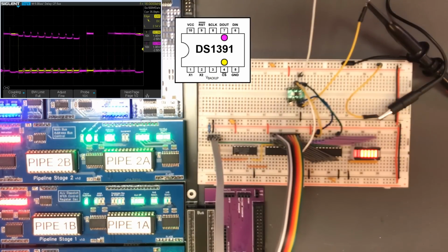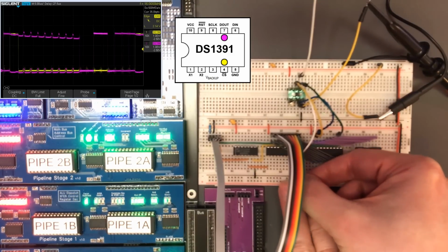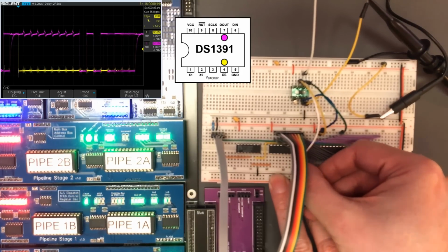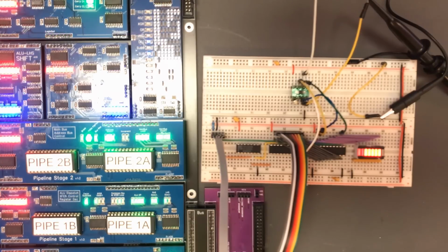Excellent. So that feels like we're seeing some rapid binary counting. It's a little bit odd at the start, but the data out is a tri-state. So only when it's outputting data will it drive the line. So I'm going to try putting a pull-up resistor in. That feels a bit more sensible. So what we need to do is modify this code so we are outputting any value we want instead of just 0 for that first half, and we're actually reading the data back in on the second half.